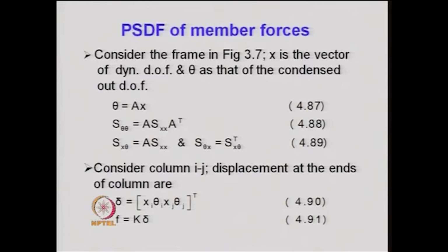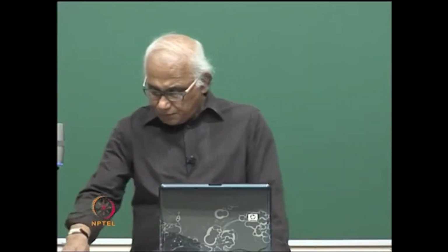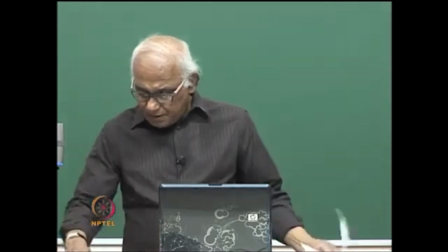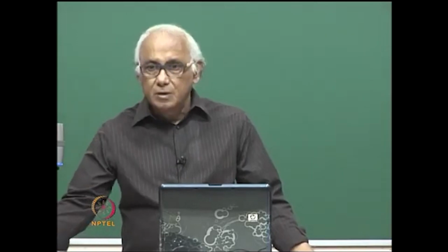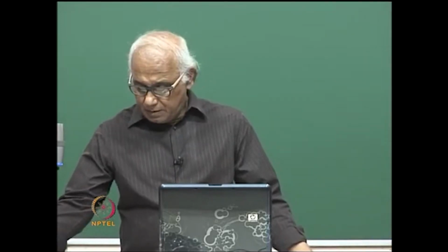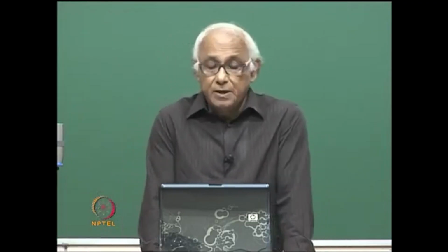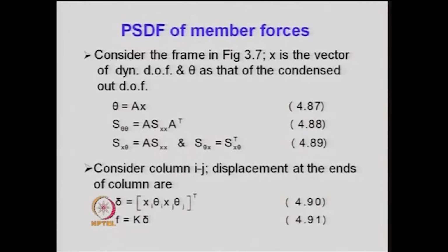Next we come to the power spectral density function of the member forces. Once we obtain the power spectral density function of the displacement, that is the displacement of the various translational degrees of freedom, then from that one has to obtain the power spectral density function of the member forces.